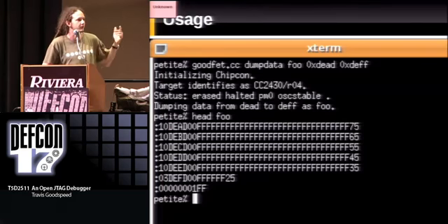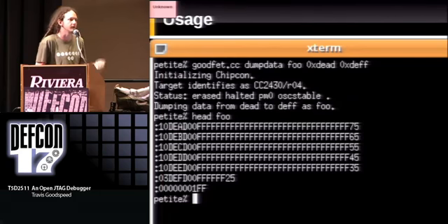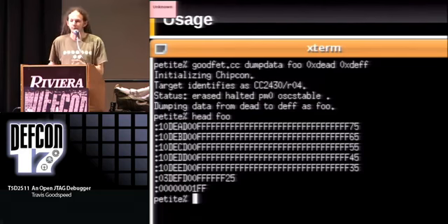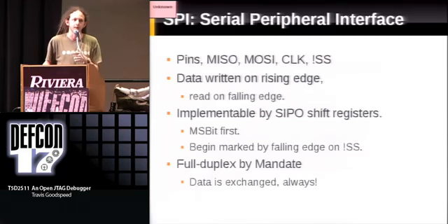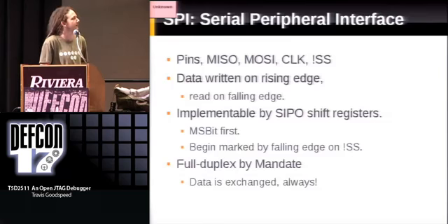This is because I chose a region of RAM that doesn't actually exist on the target chip. But I could dump software in the same way. And I can do it for multiple chips with the same adapter. So while that was taken with a ChipCon radio that supports a non-JTAG debugging standard, the same thing works with, say, the MSP430 with a rather awkward JTAG standard, or JTAG debugging implementation.